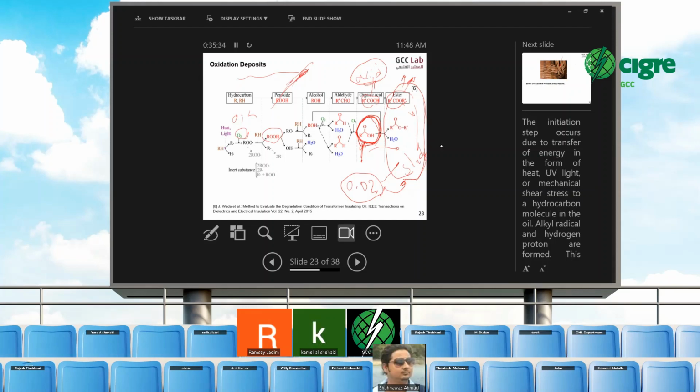One time also we found a new transformer that had a problem with overheating. Later, when they did the investigation, they found that the lamination sheet was not correctly manufactured.